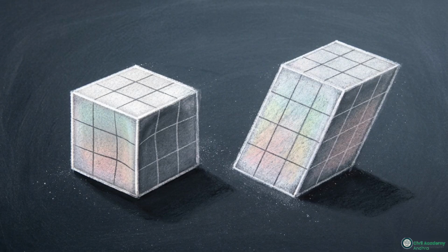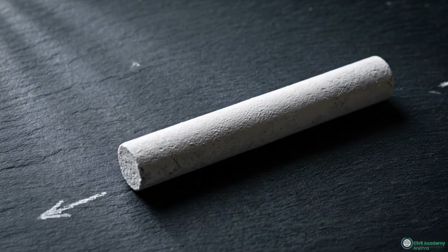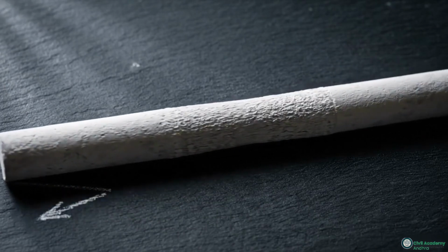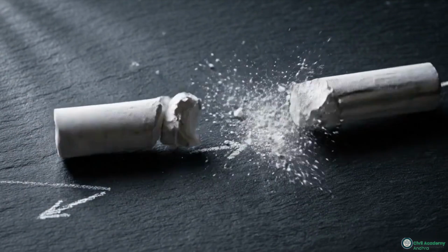Structural materials possess independent breaking points for shape distortion versus volume compression. Isolating angular shear is necessary to identify these specific failure limits. A ductile steel rod undergoes extreme tension. The rod narrows intensely at the center, a process called necking, before snapping in a classic cup and cone fracture.